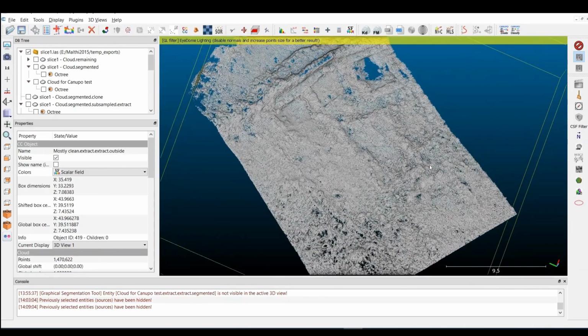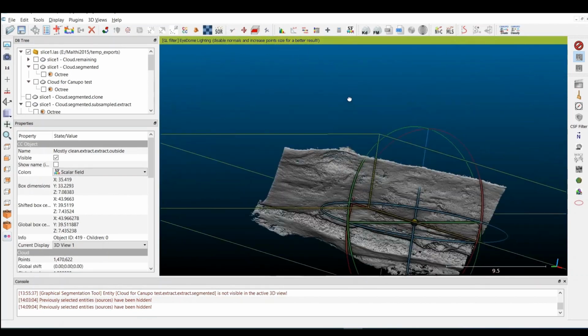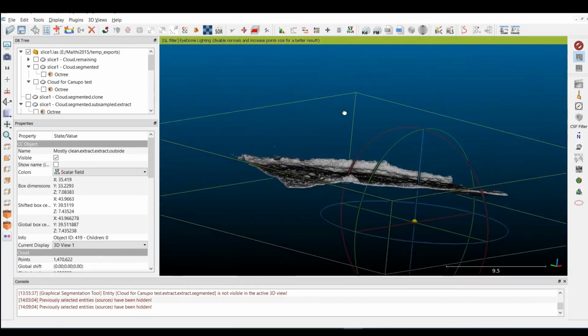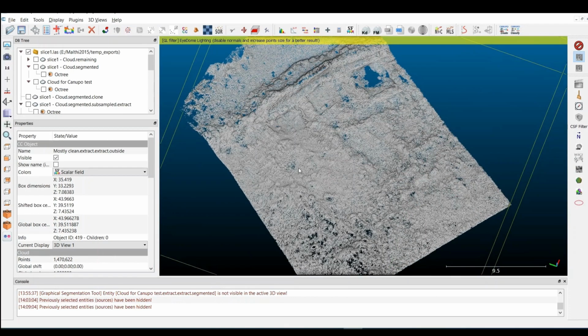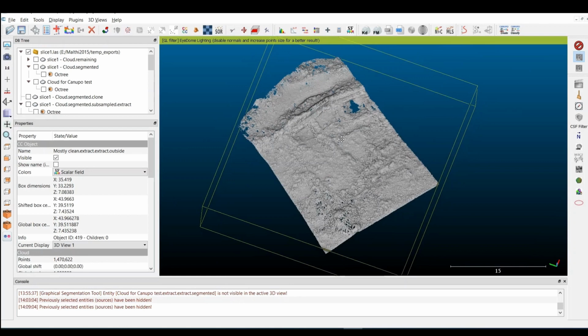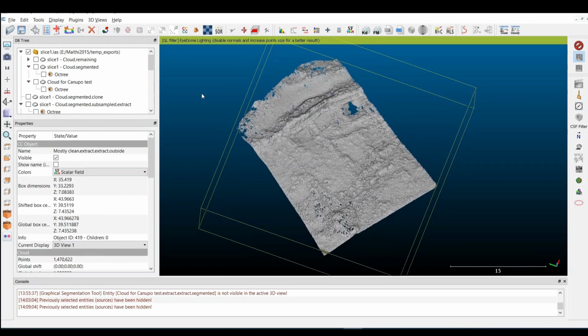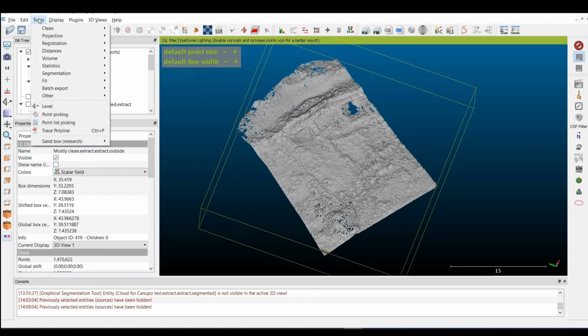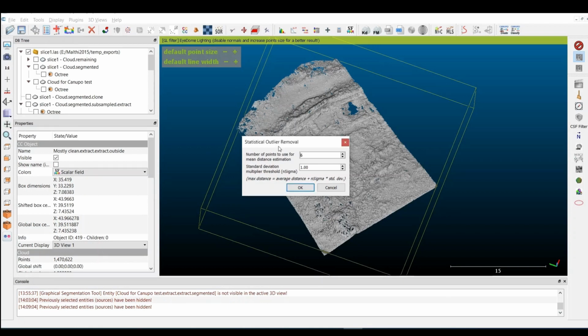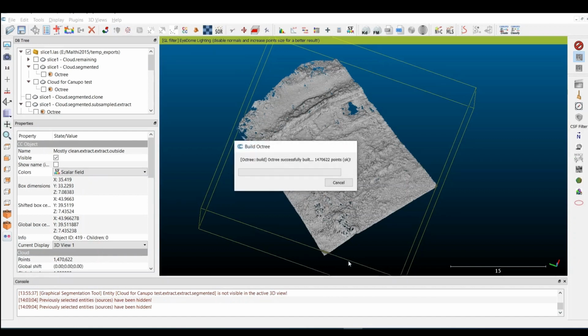So now that we've removed vegetation, there will be bits of noise that we'll want to remove as well. So this isn't really anything physically there on site during the scan, but it's more sort of stray points that are created during the process. So to do this, you'll go to Tools, Clean, and there are 2 filters here. For the SOR, it'll look for statistical outliers, so things that are basically quite far away from the rest. You can try a couple of different ways of using the filter. I'm going to go with these settings as hidden in the hint box on the exercise.